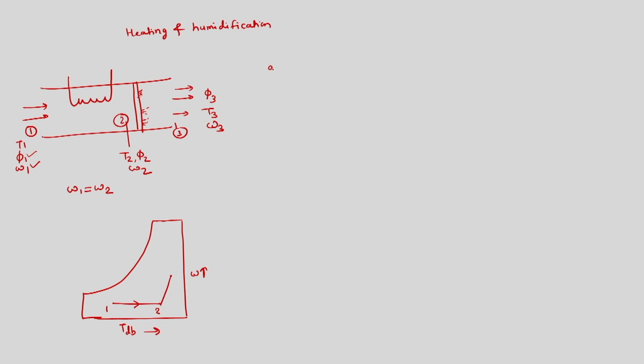Here we have to remember: if humidification is achieved by spraying steam, then T3 is greater than T2.